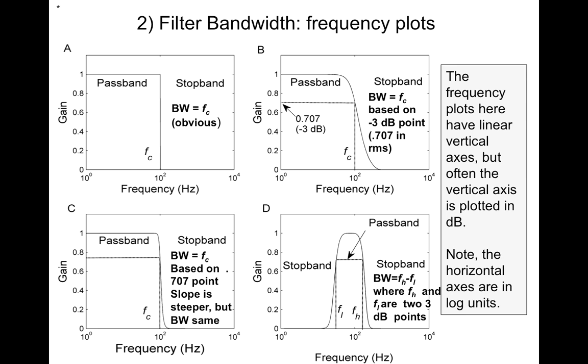So if you have a system that looks like figure B, notice that some of your frequencies of interest will be attenuated or reduced a little bit by the physical filter itself. So it's going to distort your signal, because for this range where this knee of this curve begins to where our cutoff frequencies define, you have a changing amplitude in the frequencies that are being passed.